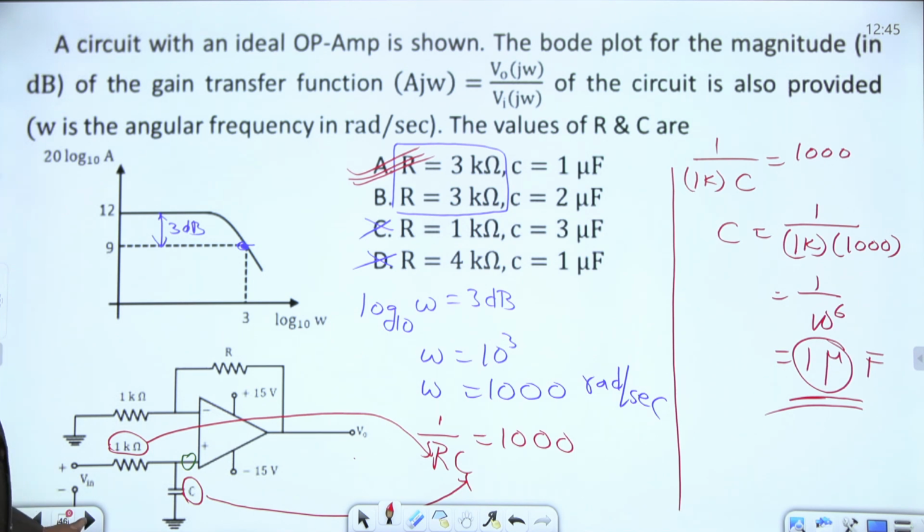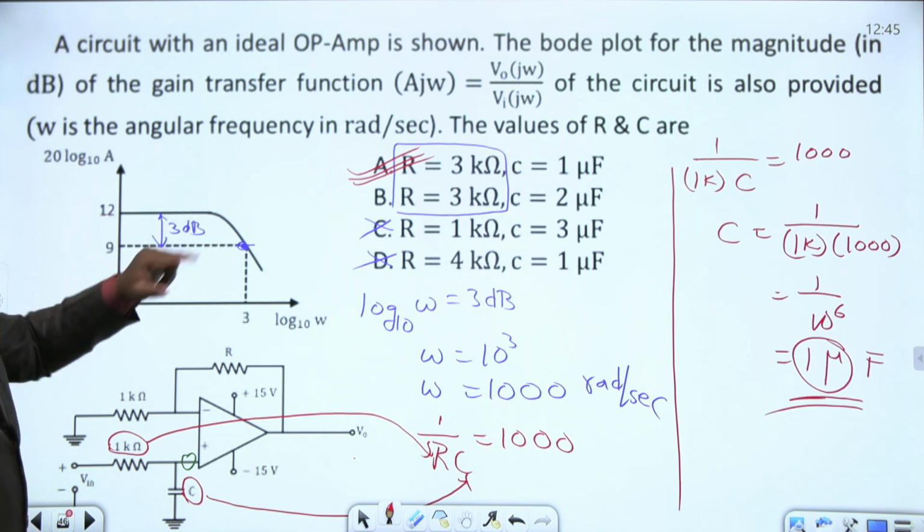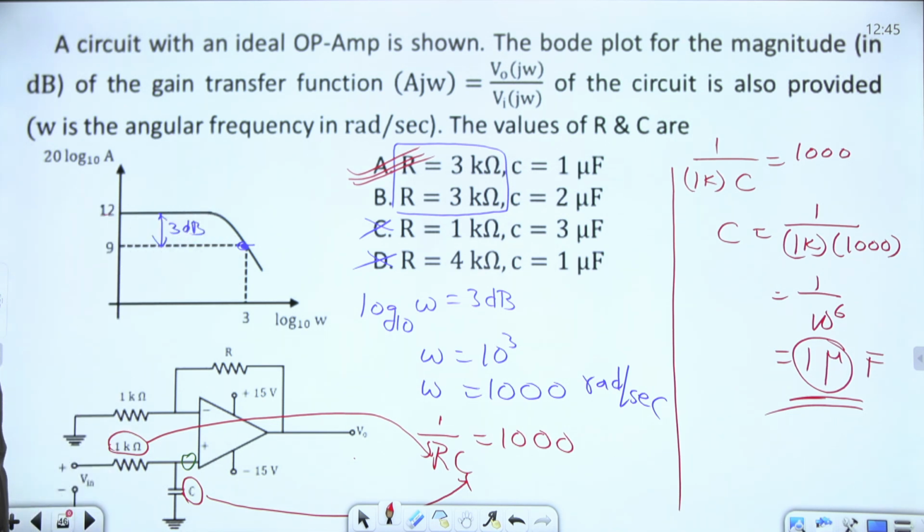First find the resistance R from this information. They gave the gain, this is a mid-band gain. From that gain, substitute with no capacitor effect here, initially.